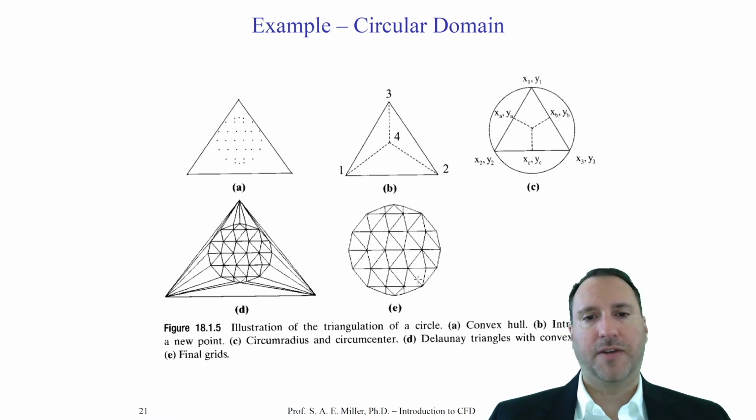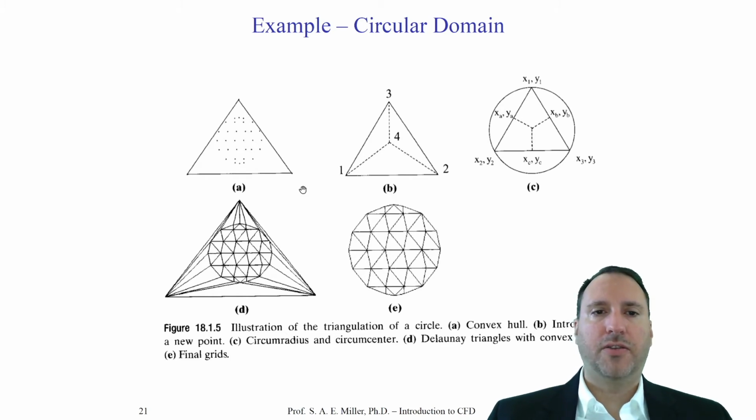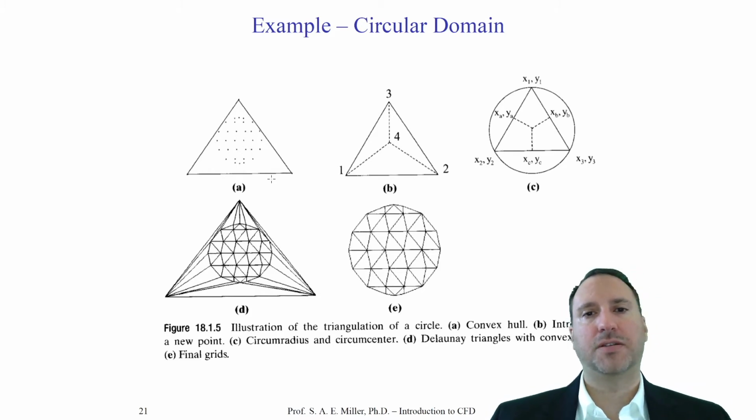without the so-called convex hull, and this would represent our final computational domain. So you can look and see graphically how these algorithms are implemented. They're implemented using, of course, the Delaunay Triangulation and the Watson algorithm to find triangular and tetrahedral meshes, which are one of the most popular meshes in finite element solvers, and of course, our favorite subject, computational fluid dynamics.